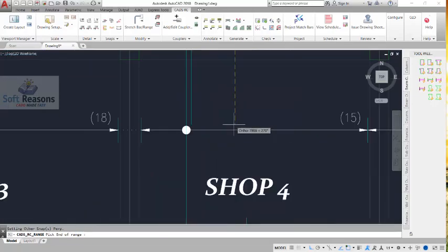It is going to stop somewhere here. All right, so pick there, concrete cover. You don't need concrete cover here, so you key in 0, because here is already inside the slab. It's not the ending of the slab. All right, so 0, enter.